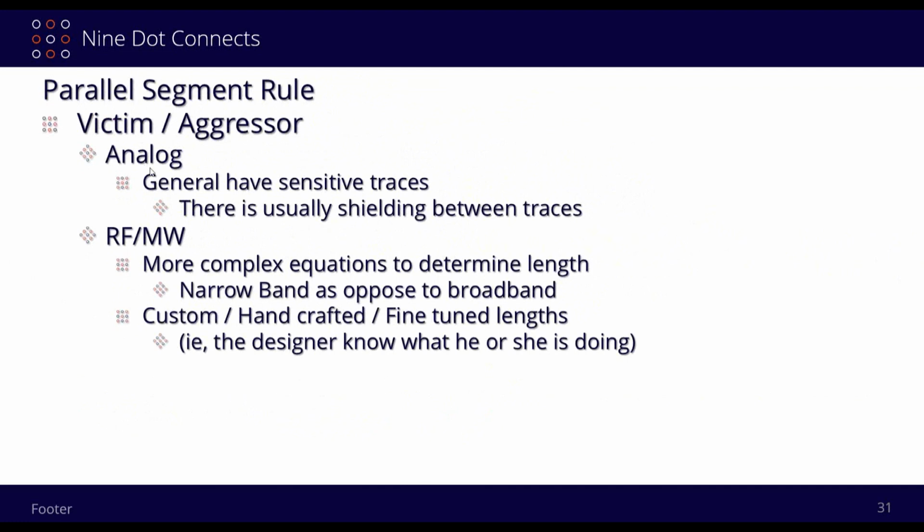Everything I talked about was about digital signals. And oh, by the way, one other thought: that 295 doesn't mean that the length has to be 295. It's just saying that a segment that's going to run in parallel should not exceed 295, out of the entire length.